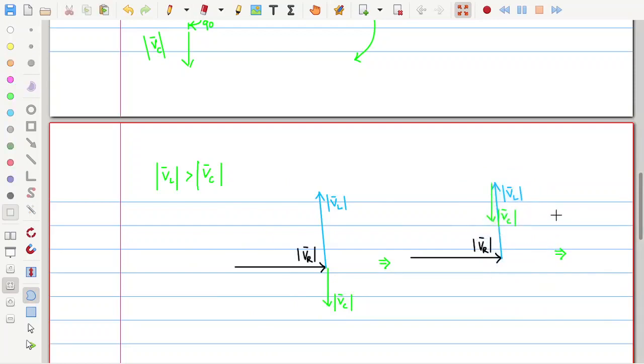If I deduct this amount of the green color length, then whatever is left out, equal to this much, is VL minus VC magnitudes. The red color one is the difference, VL minus VC. Now VR plus VL minus VC is what? The final total voltage across the RLC circuit.